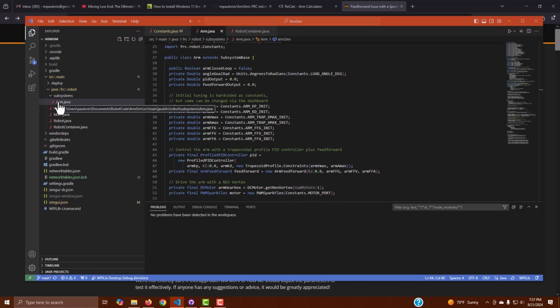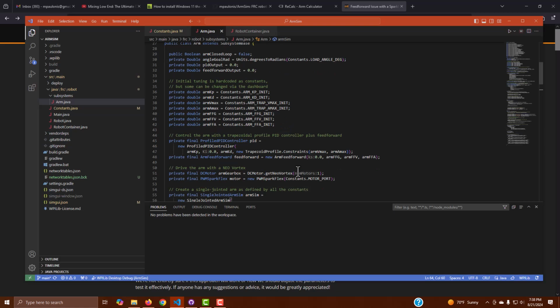That arm has an arm simulation in it, as well as simple feed forward control, as well as profiled feedback control. So you can test that with your arm and your approach to how this is done. I've implemented one way, but there's lots of other ways that you could implement control, and it's easy to test here. And if you get it working, just port it over.